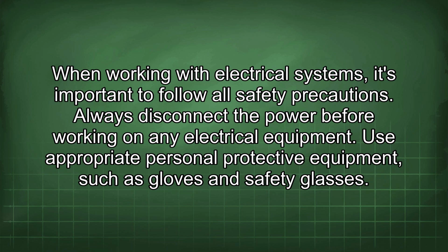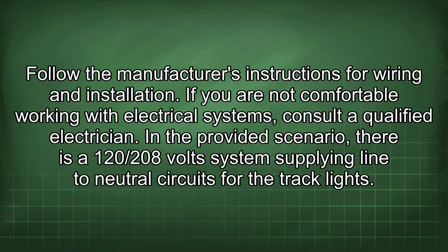When working with electrical systems, it's important to follow all safety precautions. Always disconnect the power before working on any electrical equipment. Use appropriate personal protective equipment, such as gloves and safety glasses. Follow the manufacturer's instructions for wiring and installation. If you are not comfortable working with electrical systems, consult a qualified electrician.